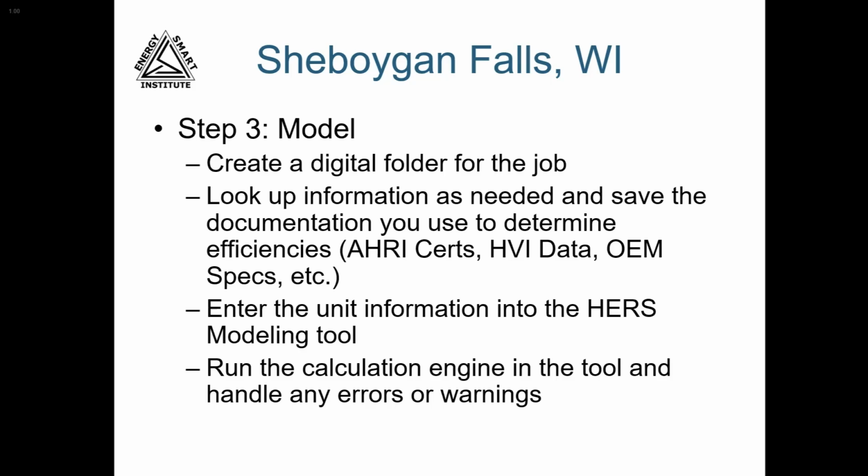Then you'll take the answers to the calculations we just completed, as well as those doors and windows and efficiencies, and enter them into the modeling software. Run the calculation engine of the software tool and handle any errors or warnings that you receive as a result. Then that is your completed energy model.